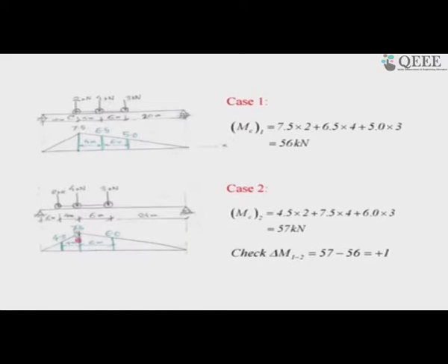Because my loads are non-uniform, I have a slightly smaller load as a leading wheel when the system of loads is moving from right to left. So, I am not so sure about the loss due to the movement of this 2 kilonewton load towards the left, but the 4 and 3, both these loads will gain in terms of positive moment as they move up the slope in the influence line diagram.